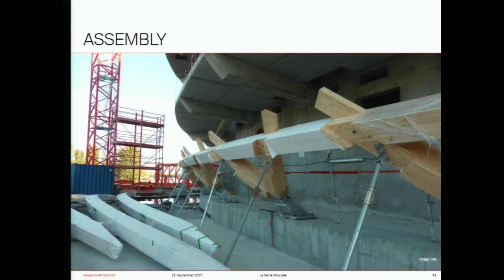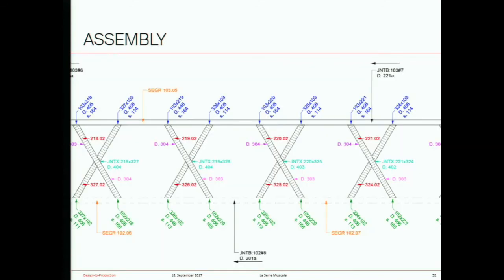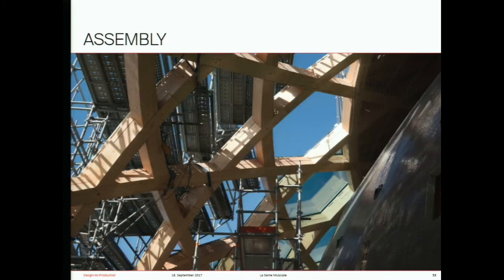Here is the first ring being assembled. You can notice the punctual supports I was talking about earlier. And you can also see on the bottom of the wood pieces the steel details. These were one of the most complex ones to develop since they combined both heavy load bearing and extremely diverse geometrical configurations. To support the team on site, we send them montage plans that are exported for every ring level. This features the name of all the joints there along with every segment.